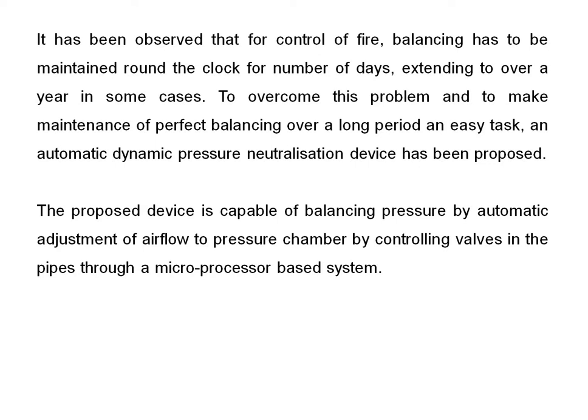It has been observed that the control of fire and the balancing has to be maintained round the clock for a number of days, extending to over a year in some cases, because monitoring is the most important thing. Only monitoring can ensure the safety of the mine, our society and our researchers also. To overcome this problem and make the maintenance of perfect balancing over a long period an easy task, an automatic dynamic pressure neutralization device has been proposed. The proposed device is capable of balancing pressure by automatic adjustment of airflow to the pressure chamber by controlling valves in the pipes through a microprocessor based system.